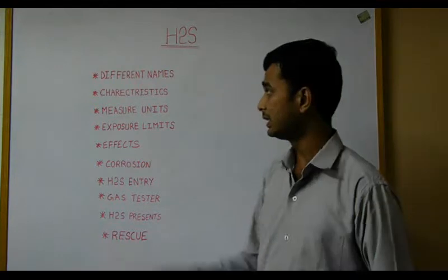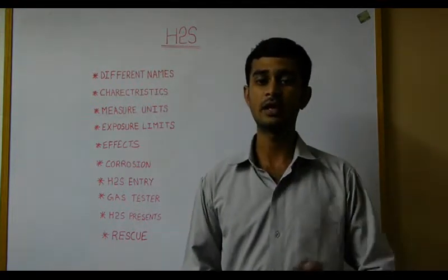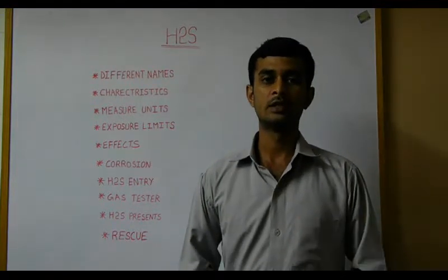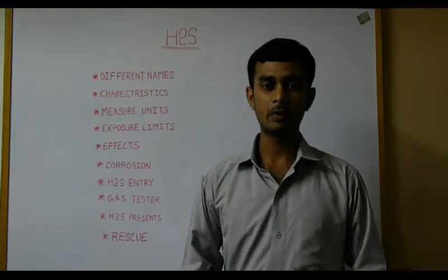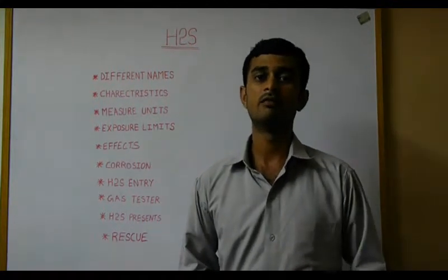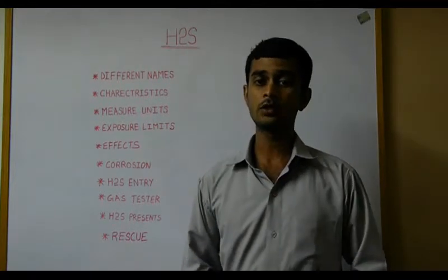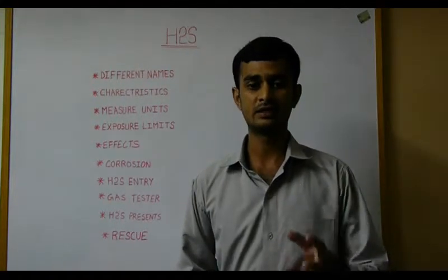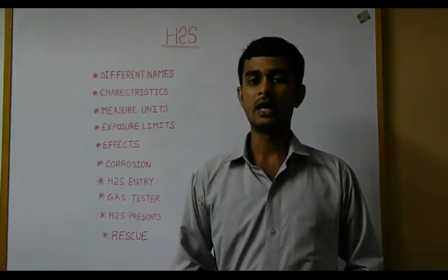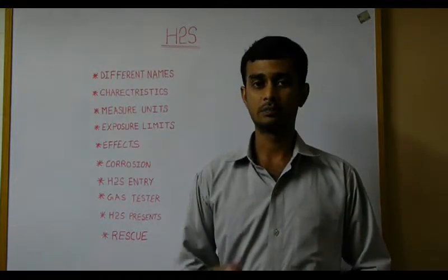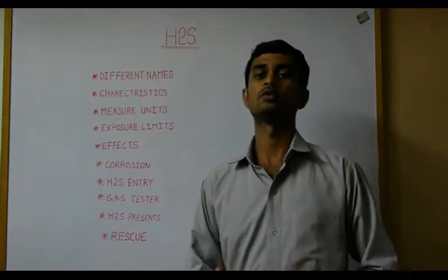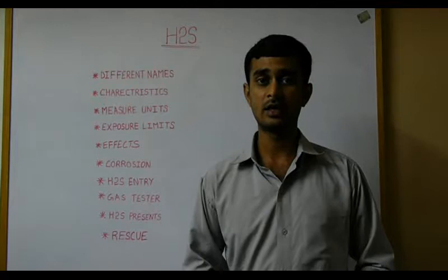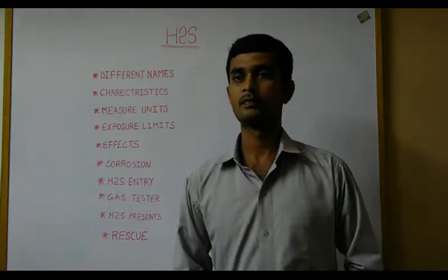Corrosion. As we see in the characteristics, this gas has a highly corrosive nature. Iron sulphide scaling is produced due to this. This iron sulphide scaling has the capability to ignite spontaneously during the surface cleaning process. Also, this scaling weakens the pipes and the fittings, even the valves and the seals. This may lead to leakage, spills, and result in exposure to hydrogen sulphide. So, sound maintenance, planning, engineering and safety precautions are necessary to manage such risks.